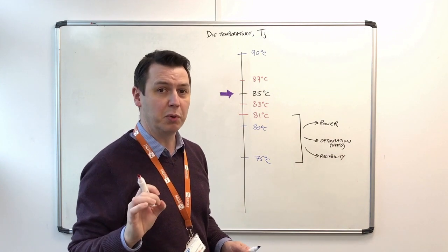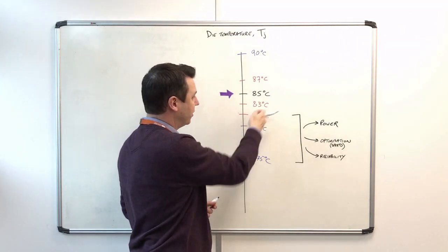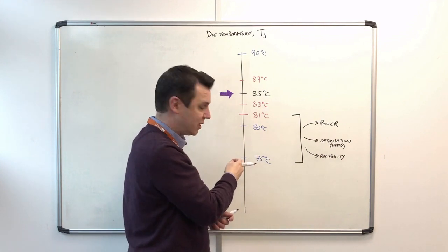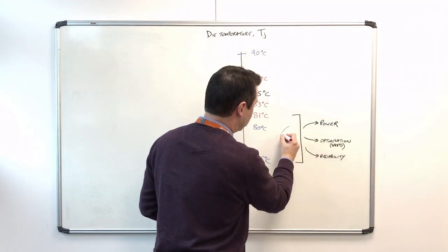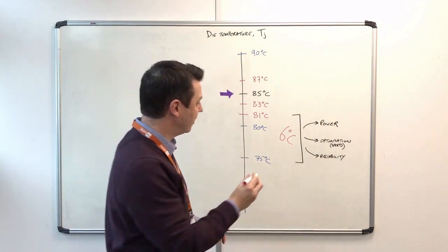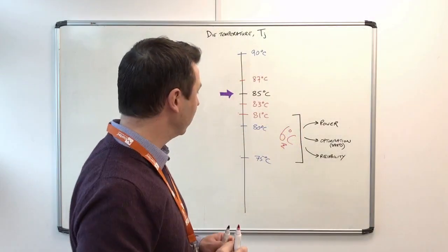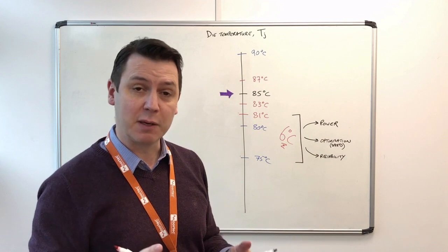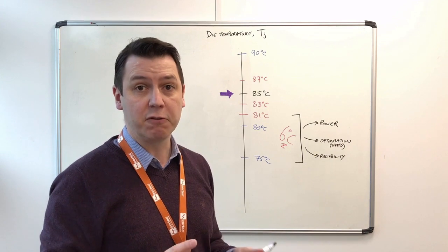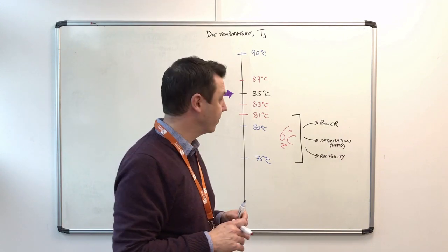So this is the important point. We're now comparing the lowest set point for software at 81 degrees C with a good temperature sensor, and for a less accurate temperature sensor, it's 75. So just by using a slightly better temperature sensor, in this case, you could be saving yourself 6 degrees C of die temperature. What does that really mean? Well, depending on architecture and the application, 6 degrees C, better accuracy, could mean anything between, say, 5 watts and maybe 10 watts of power saving. As I say, it depends on the architecture.